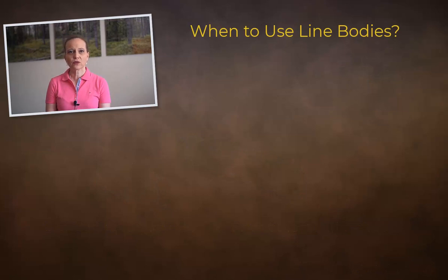When deciding when to use a line body, it is important to understand how a beam responds to different loading conditions and what types of deformation we can expect. This way, we can decide whether it will meet our simulation needs. Let's have a look at the different modes of deformation captured by a beam element.